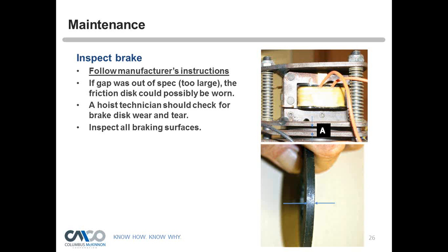When we do our schools, we highly recommend that you pop the cover off and just take a feeler gauge and look at that brake. Like I said, you're already up there on a scissor lift. It doesn't take a lot more time to just open it up and look at it. And so that's when you should do it.